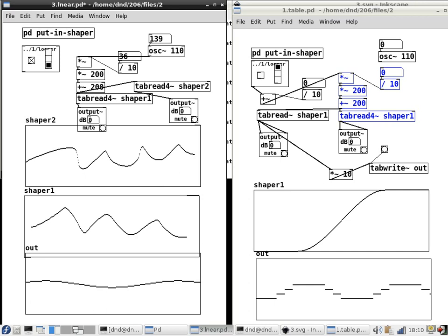This gets interesting when you start making, say, Chebyshev polynomials to come up with harmonics of sounds. You can make combinations of Chebyshev polynomials that make combinations of the sinusoids, and you can either do it by putting the whole thing in one table, or you can do it by putting parts of it in separate tables and then crossfading the results.